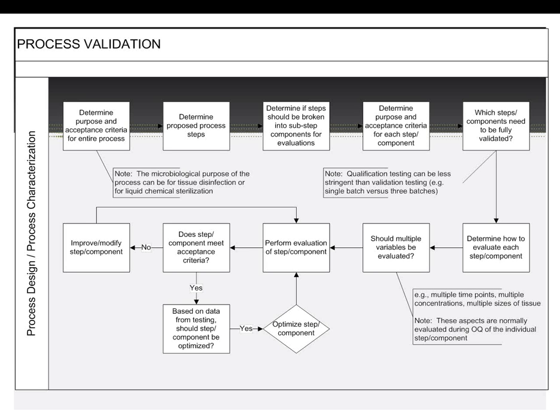And in this situation, I'm not trying to address every aspect of process validation or of a tissue process. I'm just talking about the microbiological aspects. So if each step is broken down into what microbiological benefit you are supposed to get from that step, then those individual aspects can be considered. If it is an important part of the process, as far as if that step is supposed to provide a particular log reduction or be beneficial against a specific set of microorganisms, then it's wise to make sure that you know ahead of time, based on just that step alone, what type of benefit you're getting.